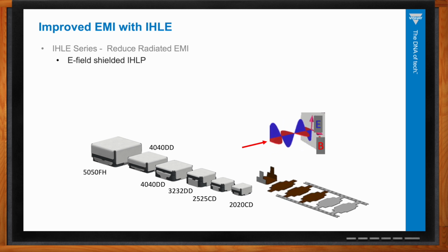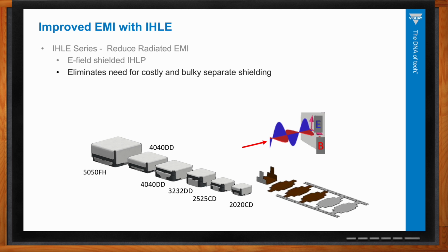Another name for it sometimes is a Faraday shield. So the idea here is that by putting the shield around just the inductor and not the whole portion of the circuit, which is normally what engineers have to do, this can eliminate the need for that costly and bulky Faraday shield that they might use to cover many other of the components. And as I said earlier, it reduces the E field by as much as 20 dB at 1 centimeter, and this is very significant for engineers.